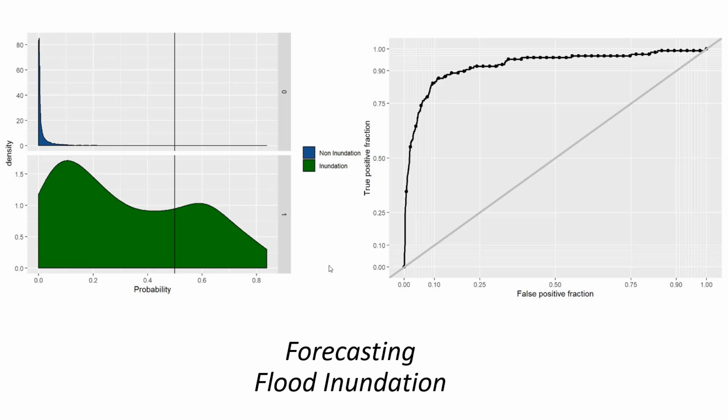Cross-validation, including training and test model evaluation, shows the probability density of flood and non-flood. The left diagram shows the highest density is near 0.1. Therefore, the threshold for inundation is 0.1. We also evaluate the model by checking the ROC curve. The AUC value is 0.97, which is extremely high. Typically, the higher the AUC value, the better the performance of the model.